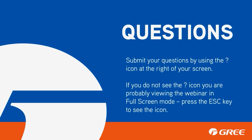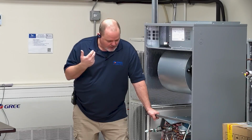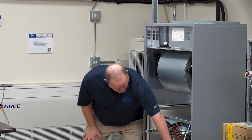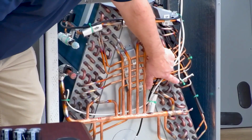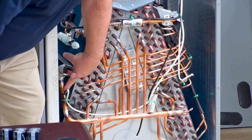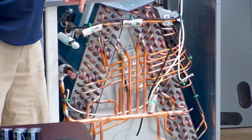All right, so now I want to redirect your attention over here to these couple units that I have sitting out here. On this coil, just like the wall mounts, the ducted, the cassettes, all of them, as I said earlier in the piping diagrams, you have an inlet and outlet temperature sensor. Right here is the inlet temperature sensor coming from our refrigerant feed in. And here is the outlet right on your gas pipe coming out.